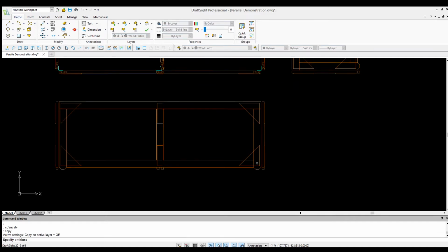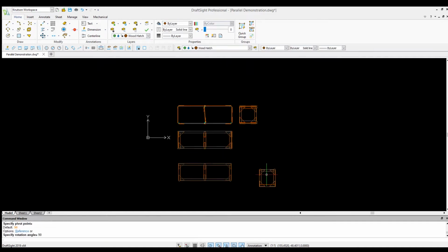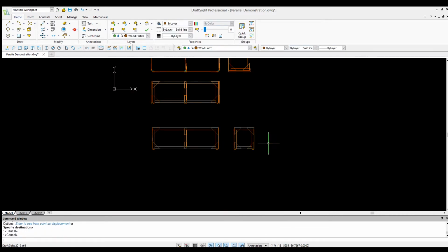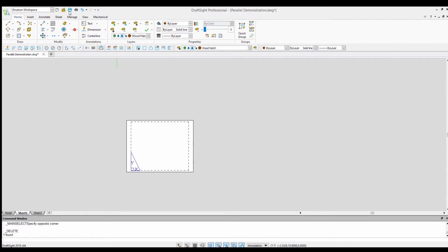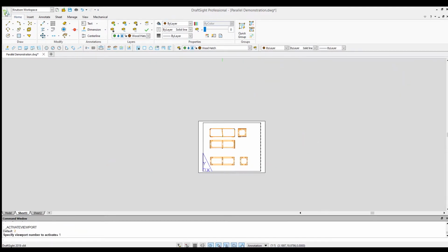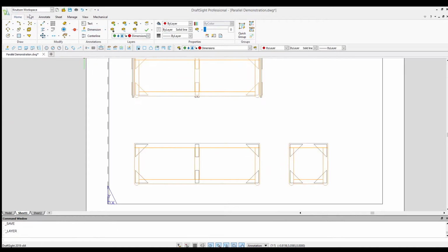When I'm happy with my plan and elevation views, I separate out component drawings. I want to show a very clear image of just a single wooden frame, so I'll copy that portion of the drawing and remove all the unnecessary information. These component drawings become the construction drafting I would hand off to a carpenter. In this case, the carpenter is me.